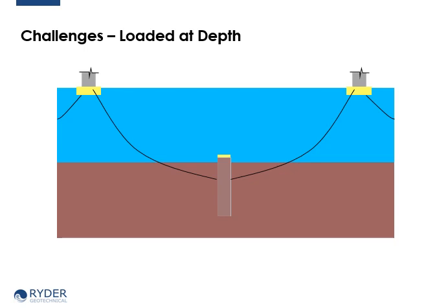Then when we look at mooring piles loaded at depth below the seabed, the capacity in this scenario is much greater, since the efficiency is higher when loading the pile at depth, because it mobilises more of the soil strength.